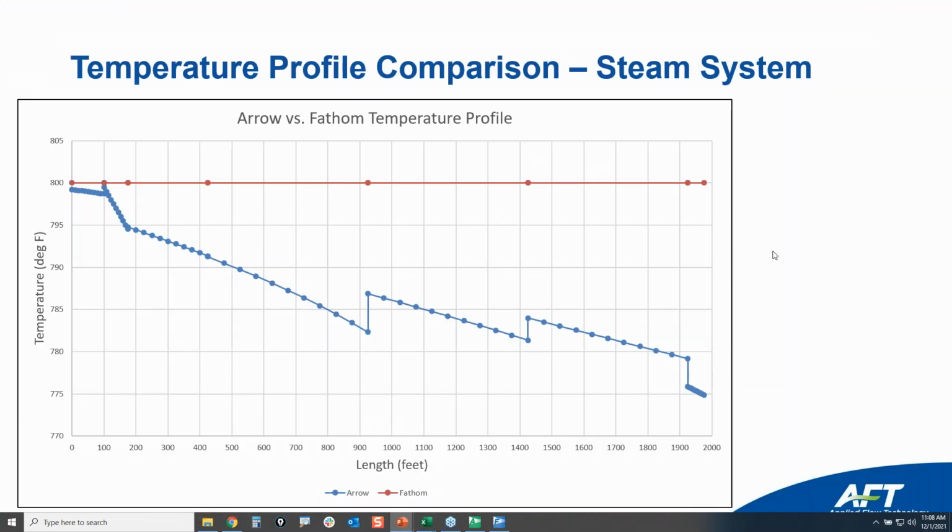And so here, you're going to see some very different results in terms of temperature. So that's something to keep in mind. Temperatures can also affect your flow rates. So if you see different temperatures, that heat transfer can have an impact on your flow rates and pressures as well. Sometimes it's small, but other times it might be fairly large. So you've got to look at it with an accurate solution to know, is your incompressible flow method good enough?